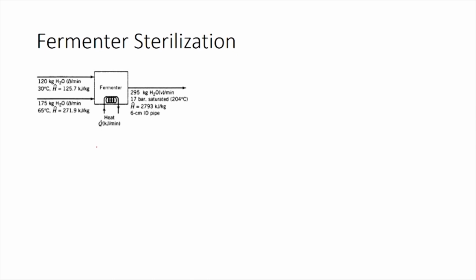First thing is for us to identify volumetric flow rate. How can we convert the mass flow rate that we have into volumetric flow rate? The steam tables give us information not just about internal energy and enthalpy, they also give us specific volume. Using specific volume, we can convert the mass flow rate which we have into volumetric flow rate.